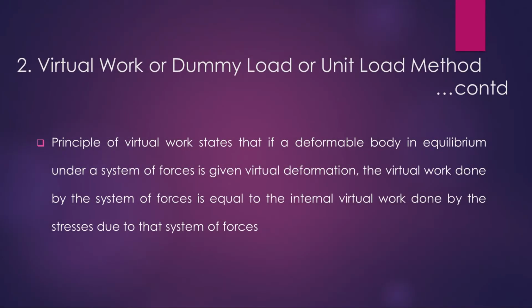It states that if a deformable body in equilibrium under a system of forces is given virtual deformation, the virtual work done by the system of forces is equal to the internal virtual work done by the stresses due to the system of forces.